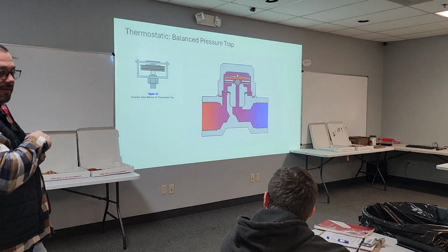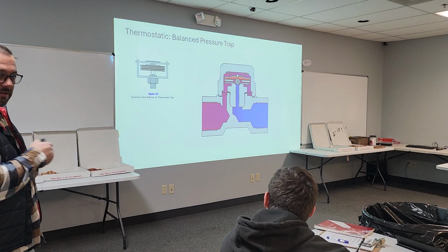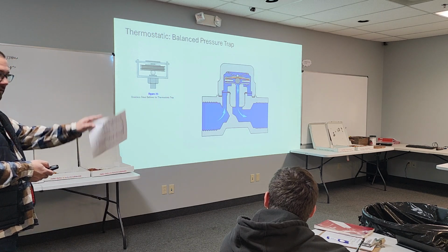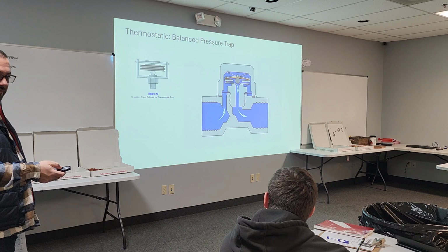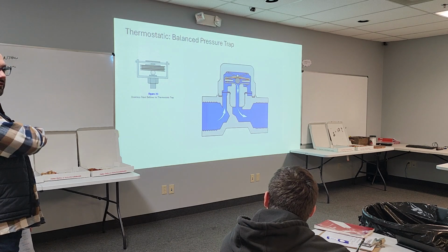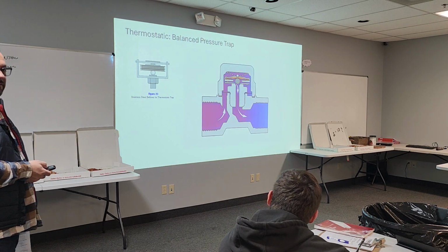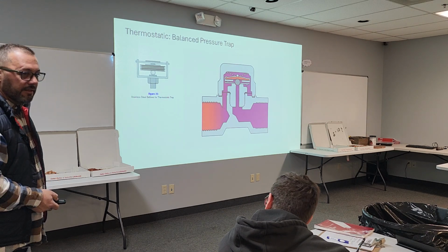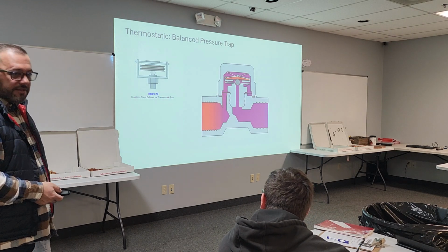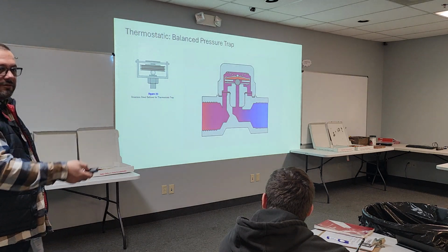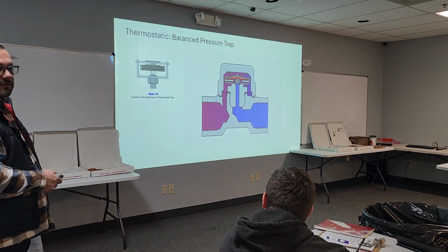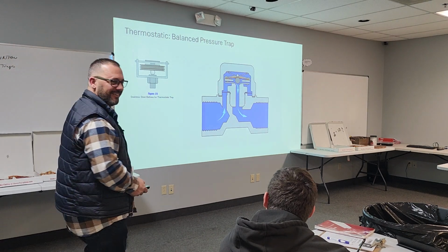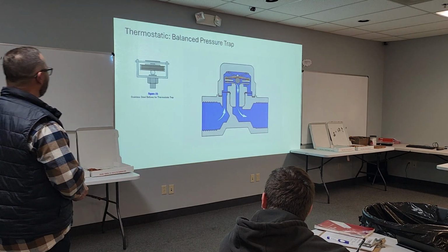But the engineering firm kicked it back and said, you gave me a steam trap, not an air vent. I said, go take a look in the verbiage where it refers to it as an air vent, and the manufacturer you've chosen as your basis of design, their air vent is only rated for 250 psi, and the body materials are cast iron. So if you want what you put in your specs, that's what we're going to use. It's been like 2 days and I haven't heard back. So, that's how that goes.